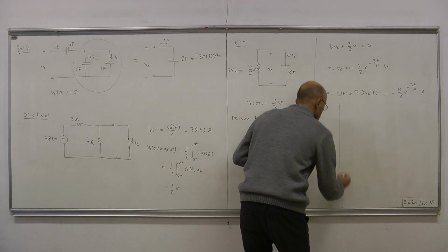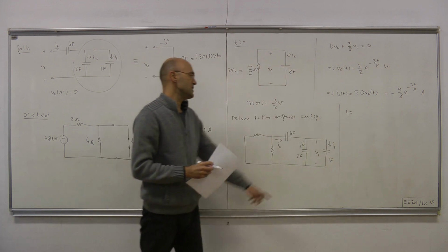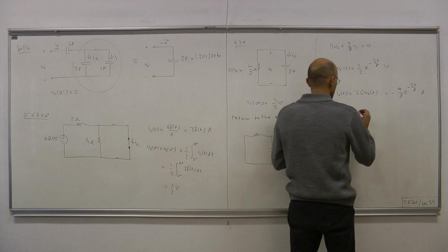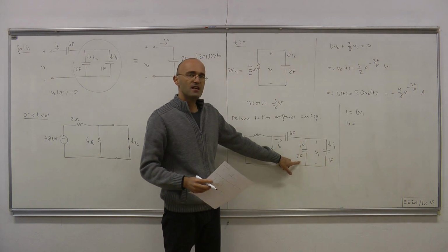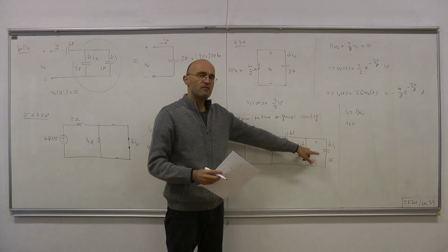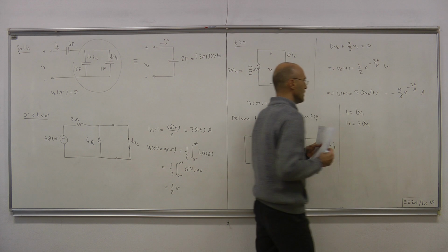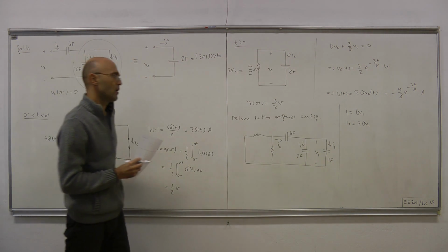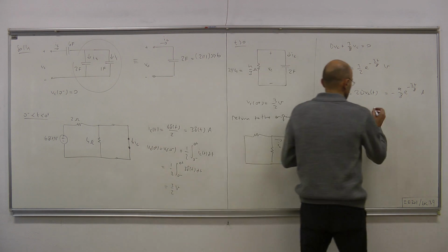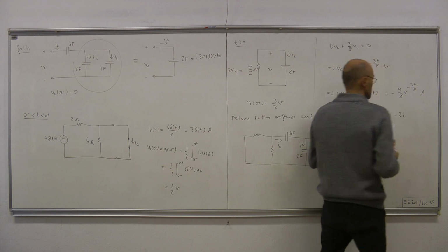So what we know is, we know I1 equals C dV1. C is 1, so we have dV1. And I2 equals C dV2. C is 2, V2 is V1. Therefore we have 2 dV1. That immediately gives us the proportion of those two currents. Okay, so I2 must equal 2 I1.